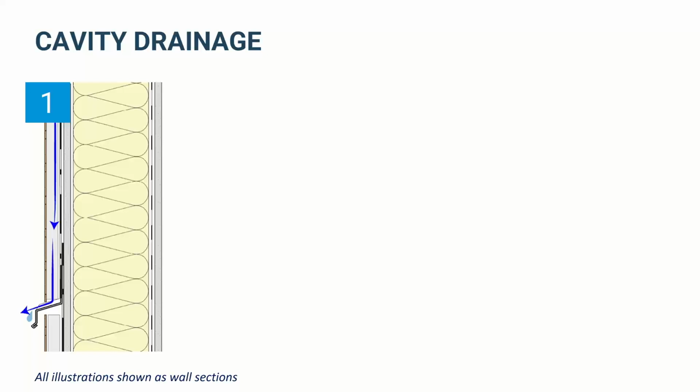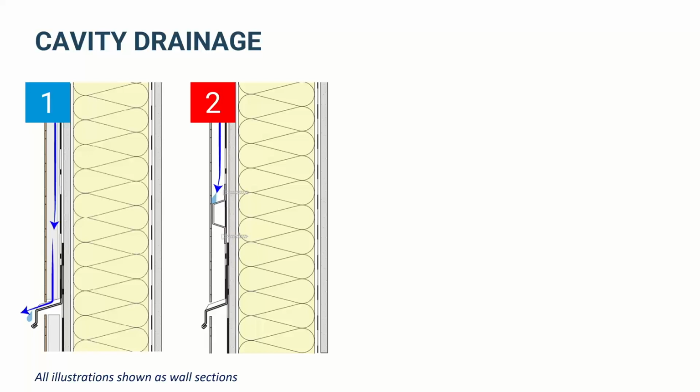So here's just some more examples here, right? This is kind of the typical flashing profile we talked about. It's really important to work through not just the assemblies but the details, right? We see this quite often. This is the vertically oriented hat channel behind a panel cladding, right? But if we had, let's say, a vertically oriented cladding and we needed a horizontal support behind it, you can see here this hat channel is now actually going to block drainage. So that's actually not a rain screen. That will collect water there. Not good, not what we want. So that blocks drainage and airflow.